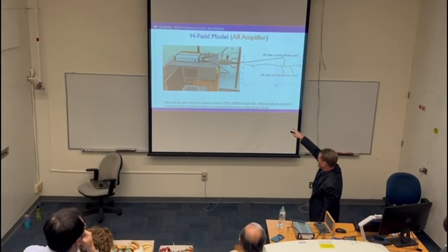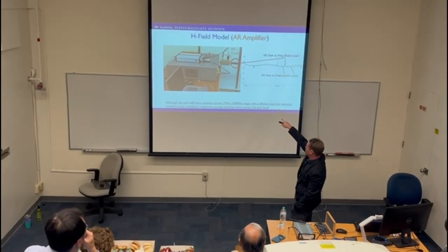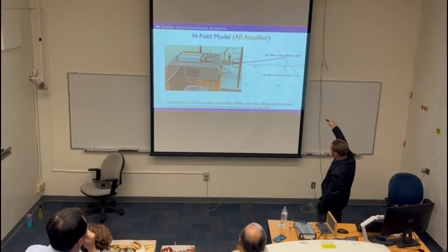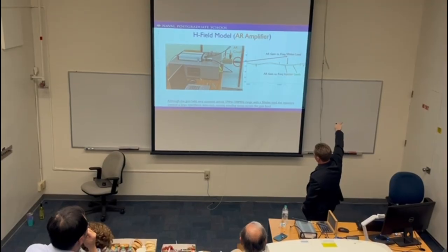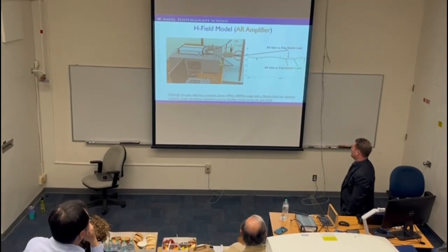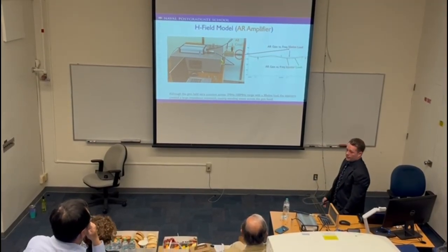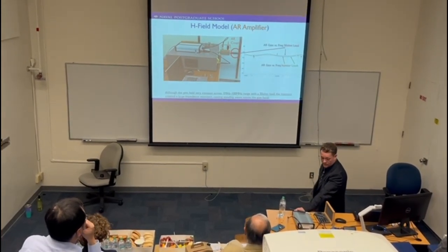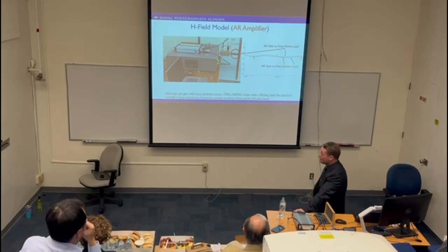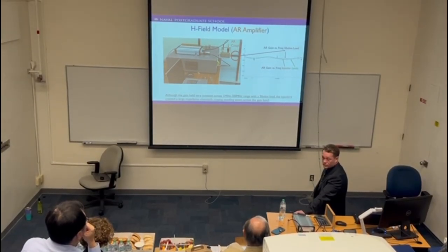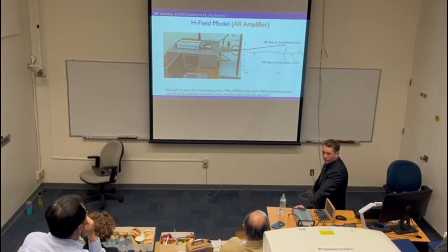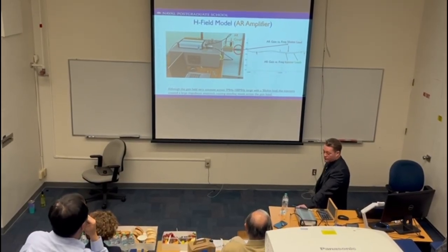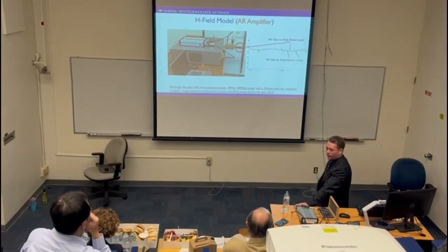In this case, as I have this 100 watt 50 ohm resistor on the end, look at that nice plot of gain versus frequency. When I have a 50 ohm load on there, it's almost perfectly flat across the spectrum. And what happens when we put my injector loads on it? Again, standing waves. I get some of this behavior, it's a horrible mismatch. But it is impressive. The AR, as they claim, is an absolute tank. It can handle VSWRs that are just outrageous, still power it, and not damage it. The reflected wave is coming back right into that output and somehow not doing any damage, ever. And they're very proud of that.